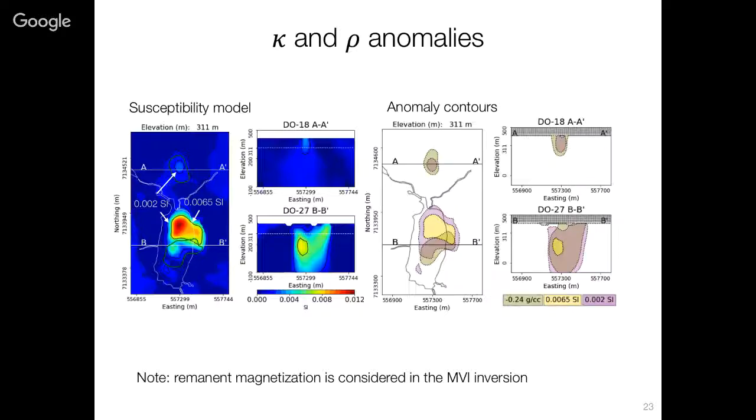First of all, based on density, anything that's less than 2.4 gives you those shells there. For magnetic susceptibility, anything that's greater than 0.0065 is in yellow, and then there's an intermediate. So here, it's still susceptible, but it's low susceptibility. So we're kind of not sure what to do about that, right? Because you could either have a unit that's sort of low, sort of mid susceptibility. It's not zero, but it's not high, right?